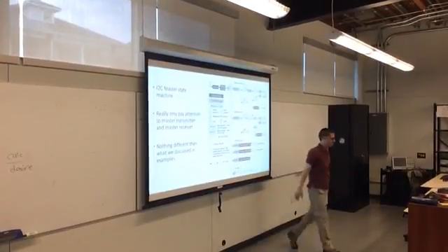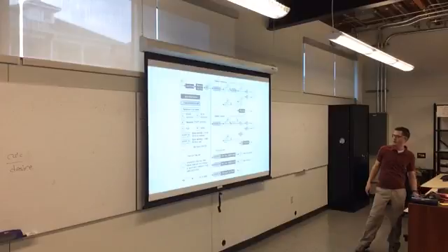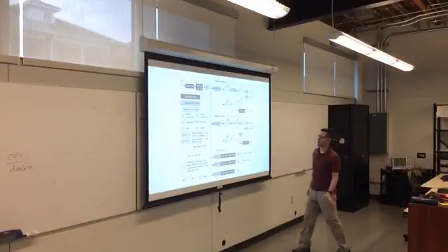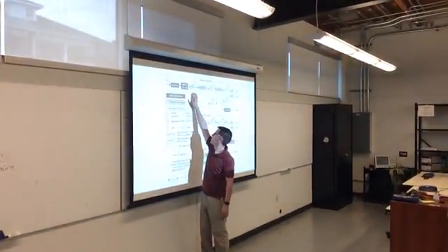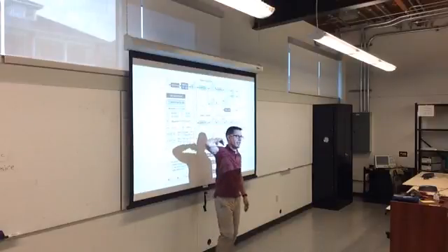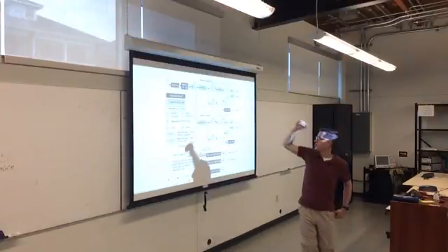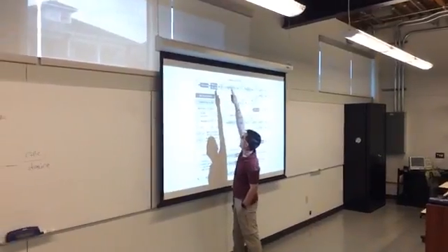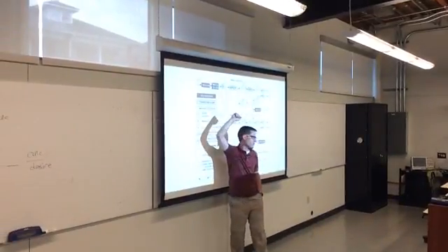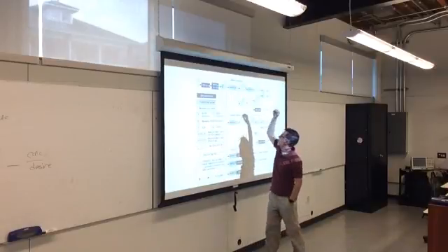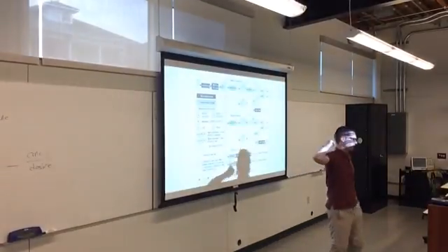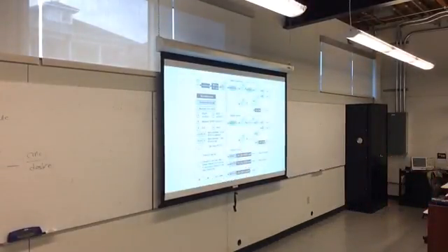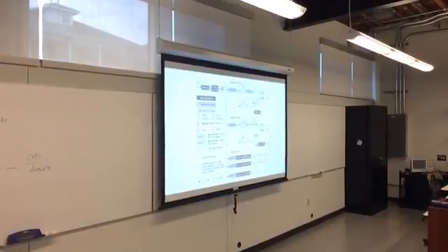And the way that you want to read this is that this is the state of the bus, and these lightly colored boxes are things that the master does. So it waits for the bus to become idle, and then the master transmits a start bit. So S there means start. And everywhere you see one of these bubbles, that is the value of the state register inside of the I2C unit. So what they're doing is they're taking all these status bits and all of these state bits and they're encoding them into a number. So if you look at that register inside your IDE, you'll see the number. It says start bit.